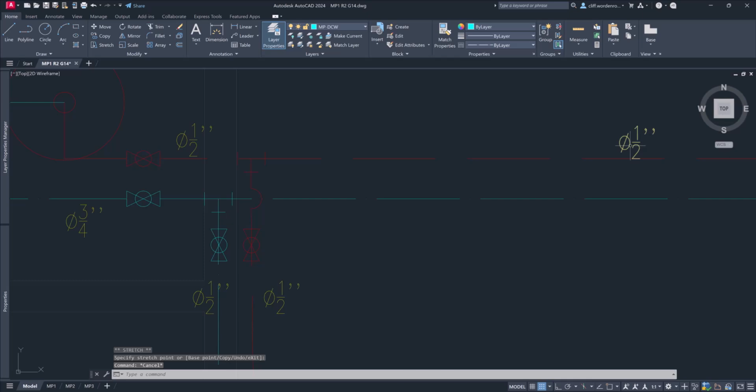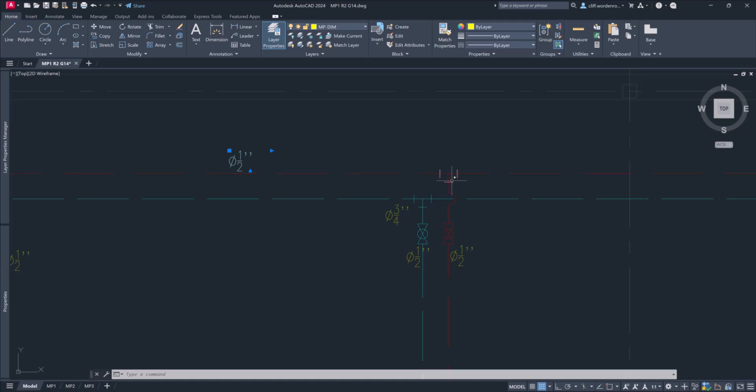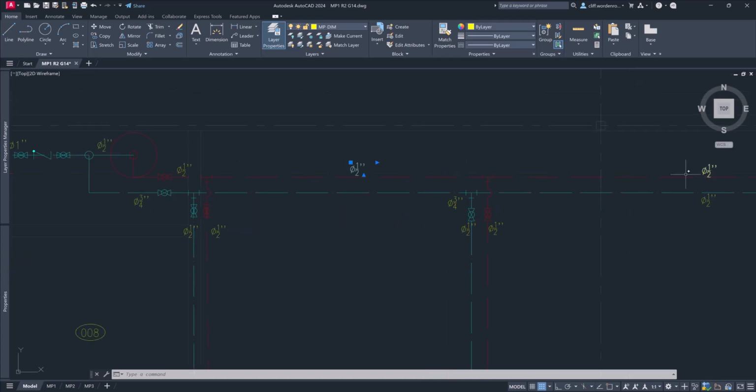You'll see designers sometimes put very little dimensions and sometimes they overdimension. There isn't really a standard. The way we like it here is that whenever you meet a T junction, you're telling me there's a 1/2 inch, and then somewhere along here, you're going to give me another one. All right, similar to here. We have a T junction, I have a 1/2, a 1/2, and a 1/2. All right, I know what it is. Okay, that's hot water. Now, yours could have been larger than 5 fixture units for hot water. Like the cold water example, I will exceed 5, right? So I'll go through that and hopefully show you what happens when you exceed 5.